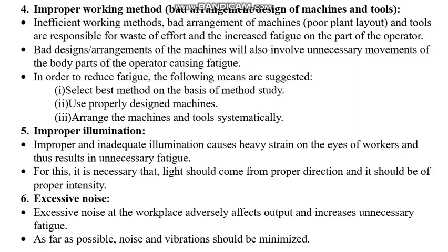Okay, so bad designs of the machines, bad arrangements of the machines will involve unnecessary movements of the body parts of the operator, causing fatigue. So to reduce fatigue because of this, what we should do is select the best method on the basis of method study. We have learned method study. Through method study, the best method can be found, and unnecessary movements and other things can be eliminated, and then use properly designed machines.